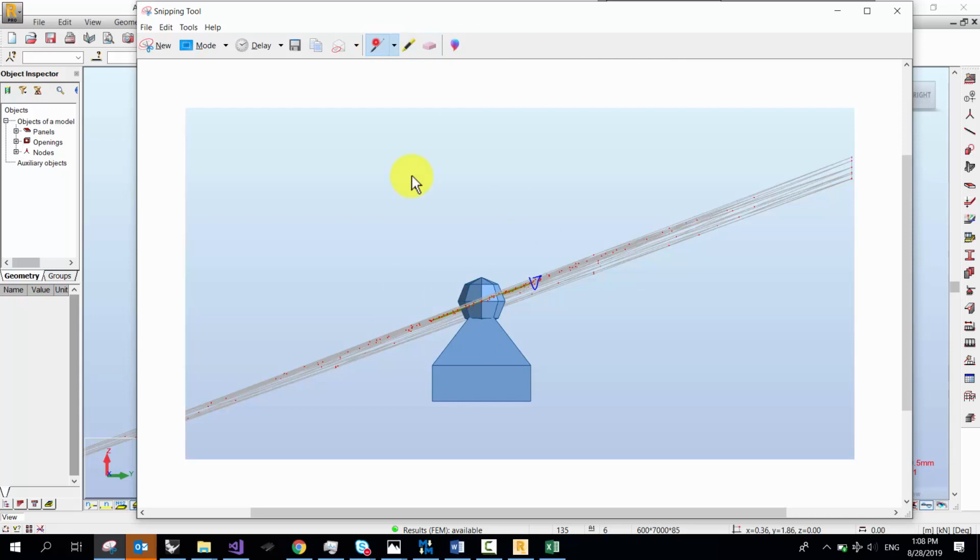So if this thing's meant to act as a pin, you can't have pins all the way along this area here, because that together acts as a fixed support that can actually take compression and tension. Now we're seeing behavior that looks very good.